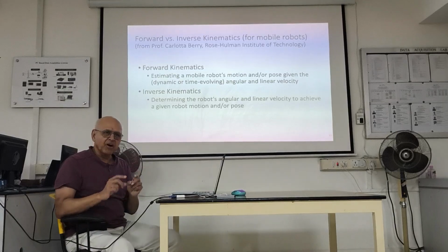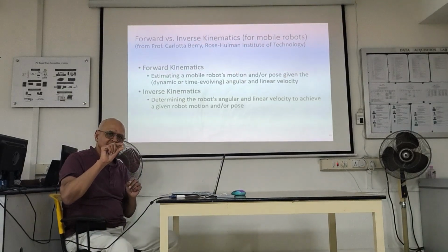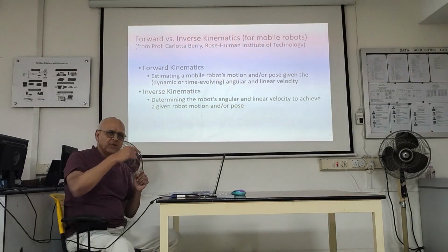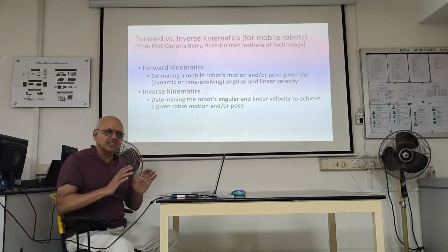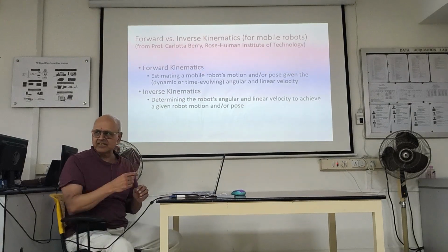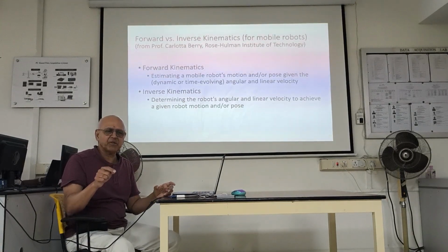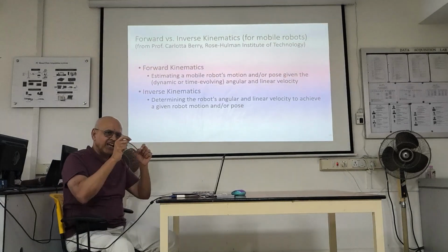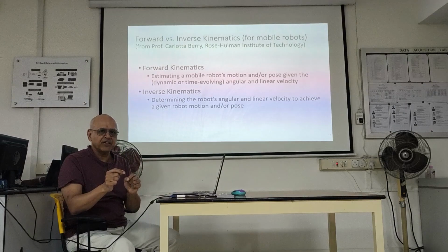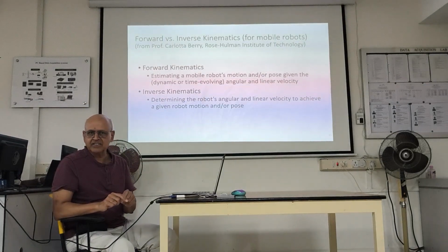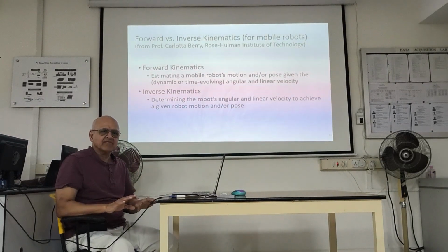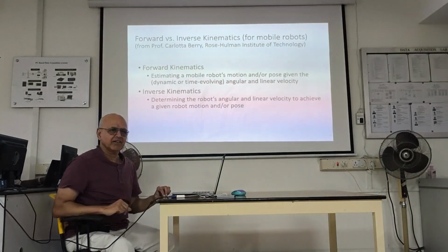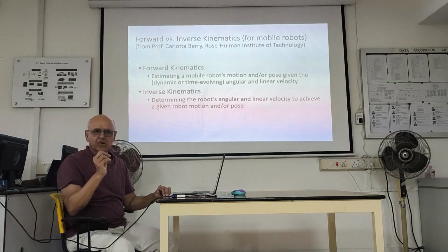So for the differentially steered robot, imagine little tiny circles, right? So the V1 omega 1 for a certain time will produce a circle, right? And between velocities, we assume that it's the same velocity. We should really be using dynamics, but we're going to assume that V1 and omega 1 is held steady till the next time. And then it becomes V2 omega 2 immediately. It doesn't in practice. But let's assume that we can assume that. So it's possible to figure out little tiny circles, we can figure out where we are, right? One solution again for a mobile robot.